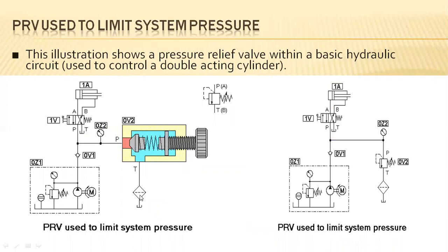And before that, we will be utilizing this filtering process, because the fluid is entering from the pump, crossing the check valve and entering the sequence valves and different relief valves, and it will be mixing with some of the dust particles that exist in the interlines, which will be filtered out with the help of this filter and drained back to the oil reservoir, and the same fluid will be put to the system again.